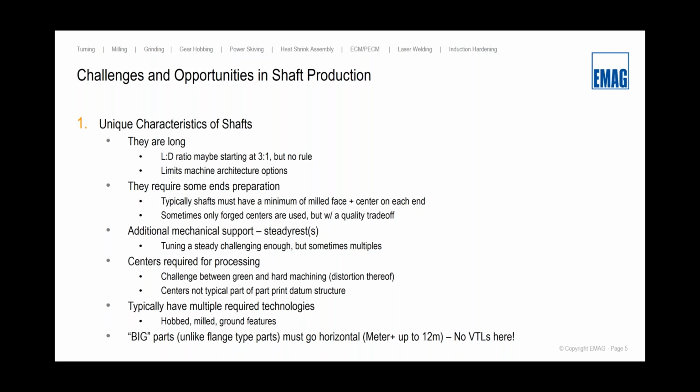Going back to centering, very challenging to deal with these, more so from the fact that your final part print, as it's designed for that component to go into assembly, 9 times out of 10, the centers are absolutely insignificant to the function of that component. However, in many components today, those centers are the datum structure from that Op10 process through your finish polishing or grinding operation.